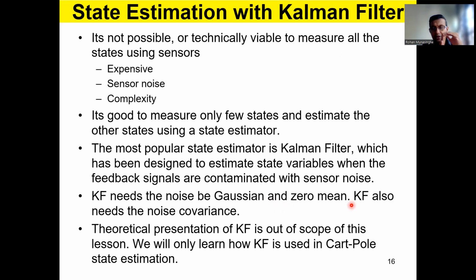Mean error is zero, and it goes negative, positive by equal amounts. When you get a negative error, you get a positive error the next moment, like that. It swings back and forth around zero. If you add all the noise parts of the sensor signal over a long period of time, they add up to zero. That's why I call it zero mean.